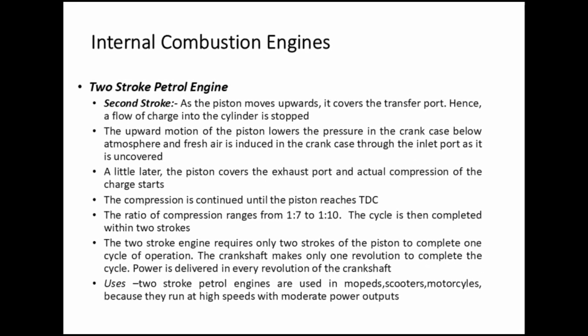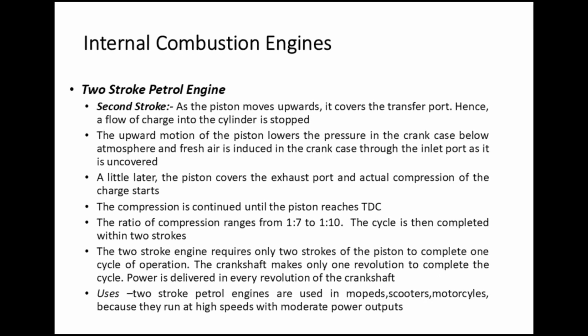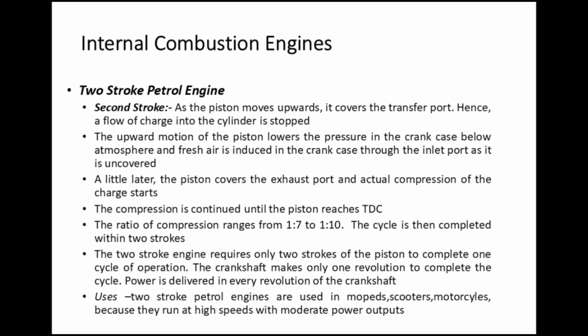Internal combustion engines. Two-stroke petrol engine. Second stroke. As the piston moves upwards, it covers the transfer port. Hence, a flow of charge into the cylinder is stopped. The upward motion of the piston lowers the pressure in the crankcase below atmosphere and fresh air is induced in the crankcase through the inlet port as it is uncovered. A little later, the piston covers the exhaust port and actual compression of the charge starts.